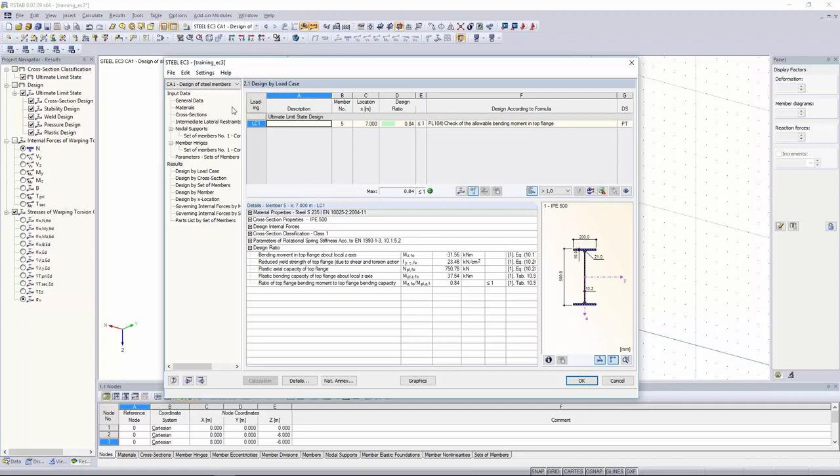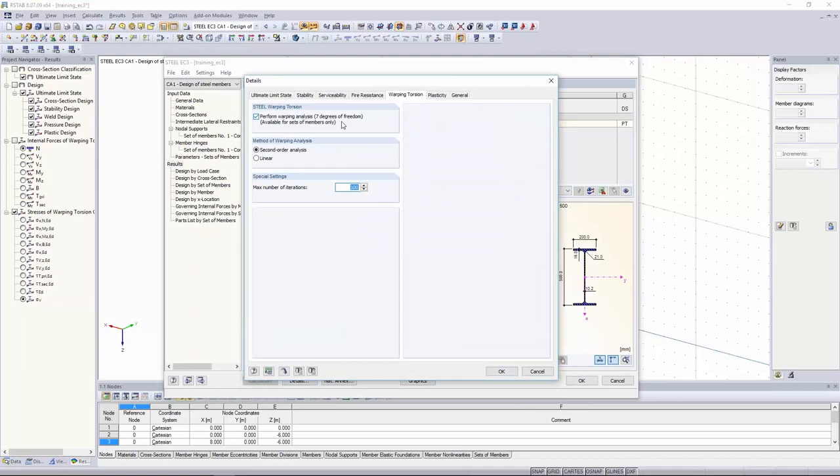If you have a bending moment around the Z-axis, if you have torsion, which is a big topic, if you have unsymmetric sections, shaped thin sections, all the general sections, and you have a loading with bending and compression, you might need warping torsion, and this gives you a solution to get the steel stability design done all in this module.